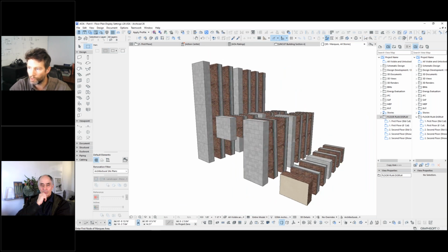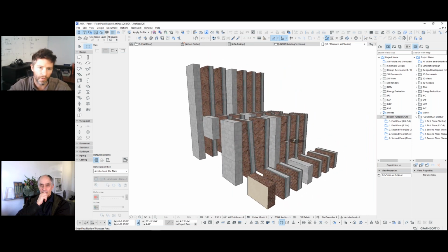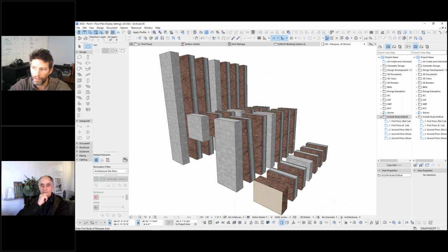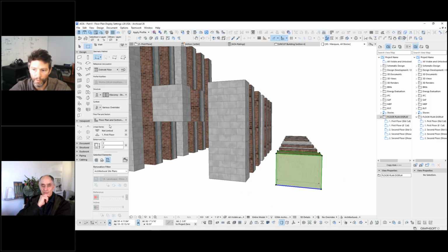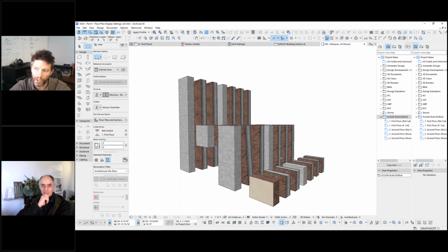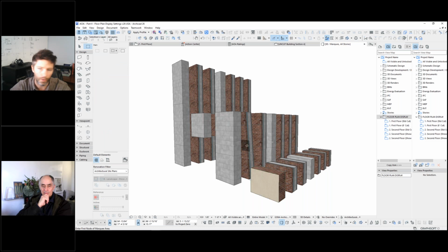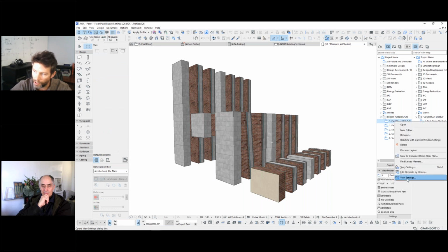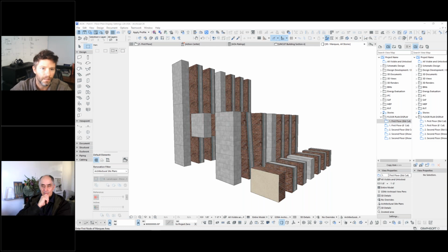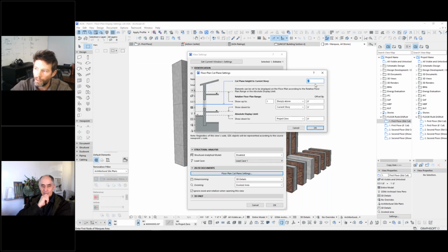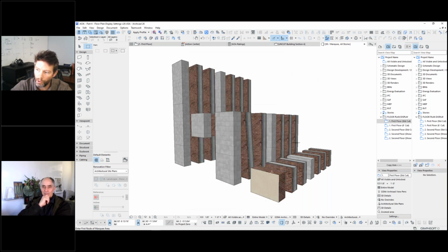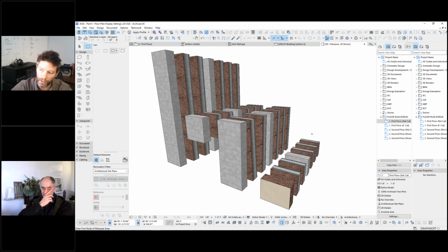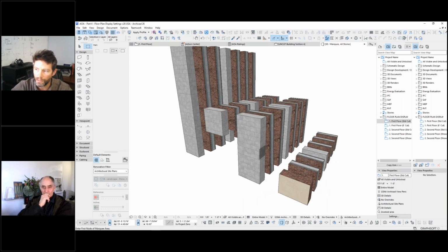So the whole purpose of this was to set up a grid or a matrix of different types of walls. In this case, some were modeled only a few feet tall, 3 feet here, which in the US version, our standard cut plane, if we go into our view settings, is set at 4 feet by default. Because these are below the cut plane, it allows us to look at different floor plan display settings that we can assign to them.